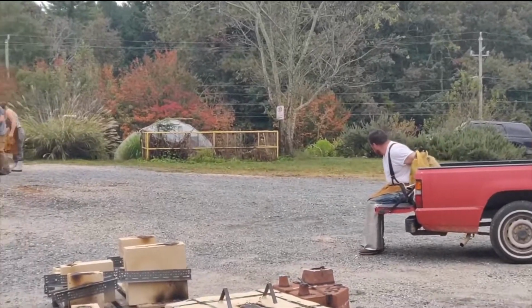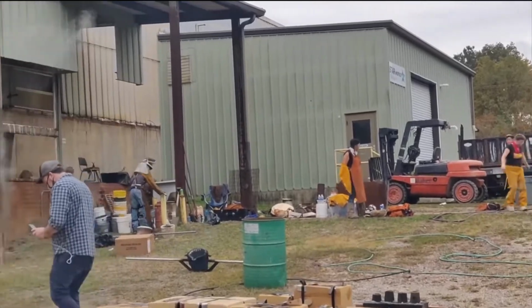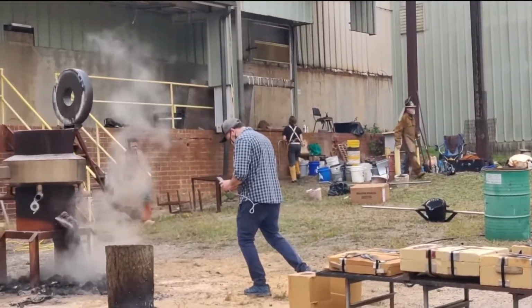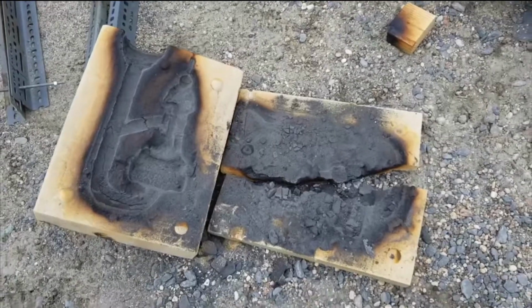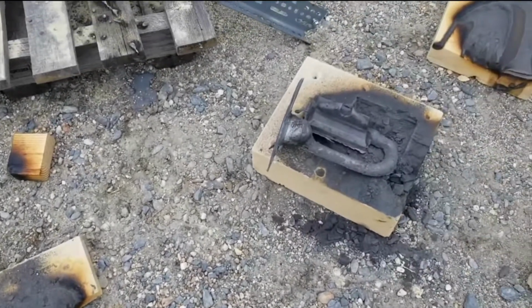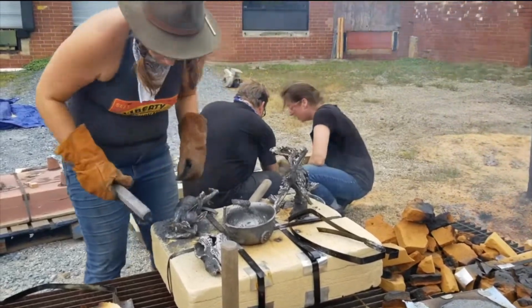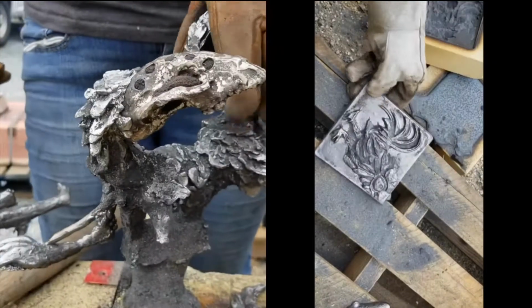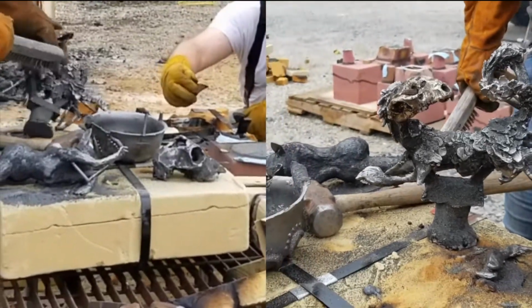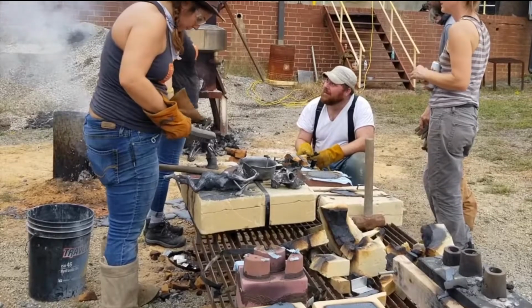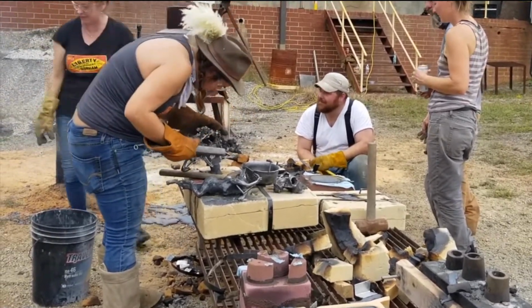The casters usually have a celebratory drink and take a break while they wait for their pieces to cool a little more. Like I said before, iron solidifies fast, so within an hour after pouring you can usually go ahead and open your molds. The artists get to see how their pieces turned out and often go ahead and start cleaning with wire brushes. Any unwanted sprues or extra metal flashing sticking out in odd places will be cut off and ground down later once everything is completely cooled off.